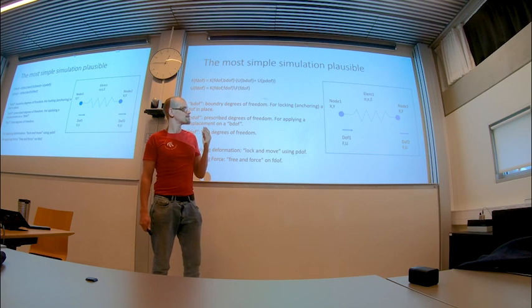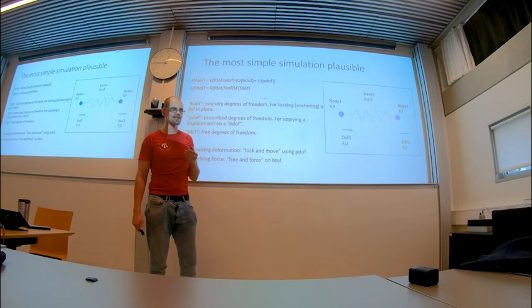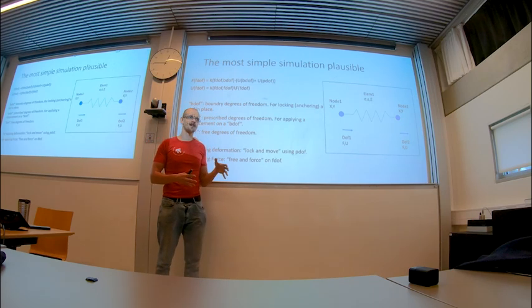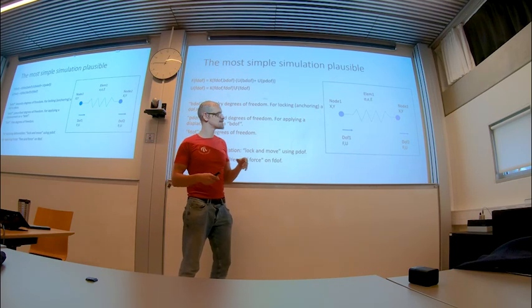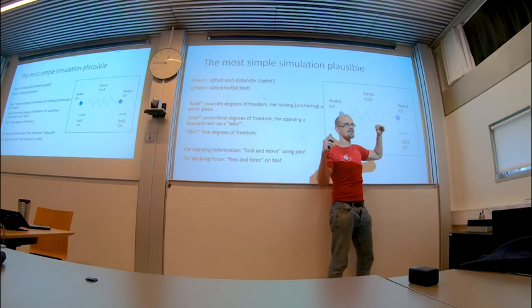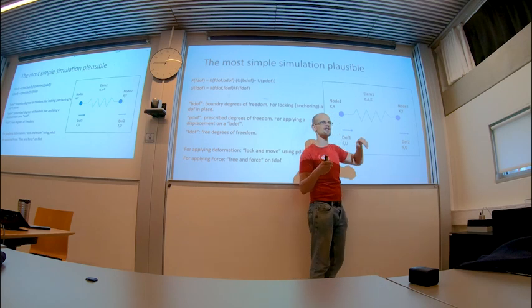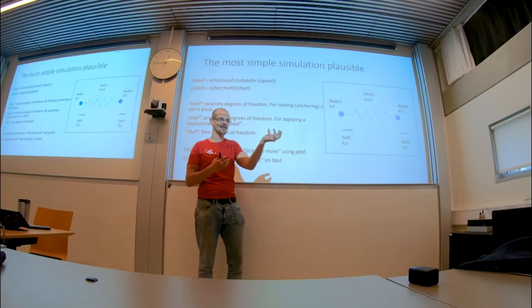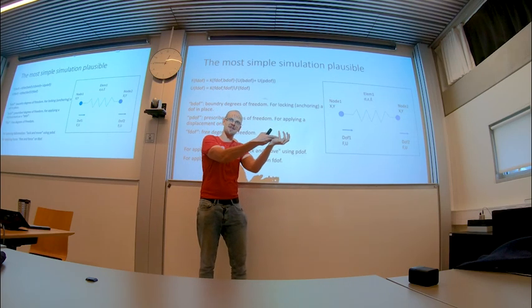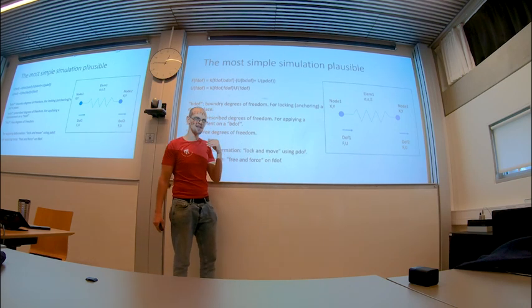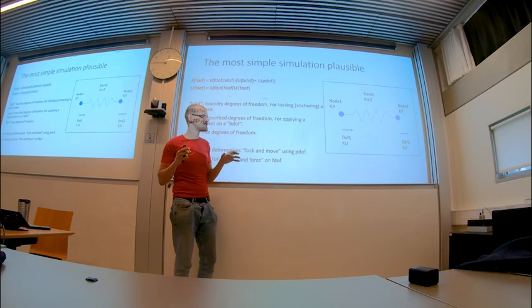And then it doesn't change once you add plasticity. It still runs on top of this elastic background, elastic core. But what you do with plasticity is you generate artificially some internal forces. I'll call them internal. They also call them plastic increments. But plastic increments is just a value that says, I'm going to apply a force that produces this amount of plastic deformation. That was something that was really hard for me to get when I was studying this topic. It was so heavy in math.